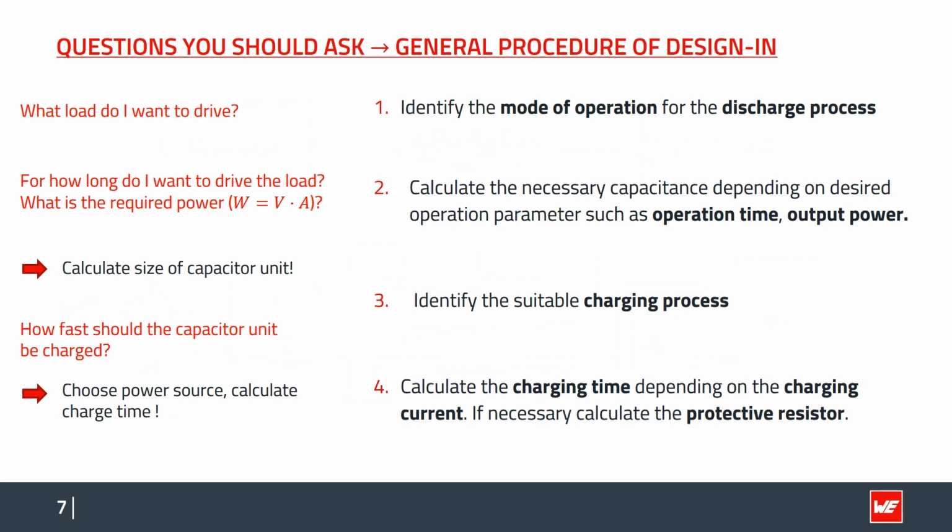So if you want to design a supercap unit, you may in most cases follow a certain procedure. The first thing you should ask yourself is, what load do I want to drive? How much power at which voltage do I need? And for how long do I want to drive the load? What is the required power in watts?